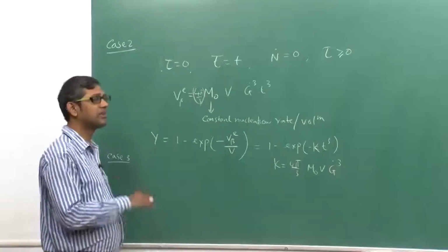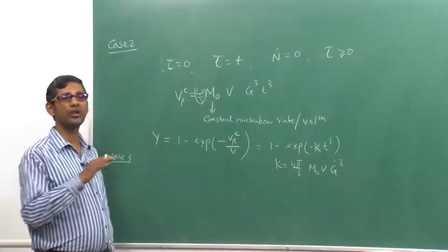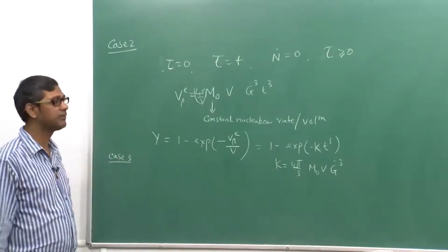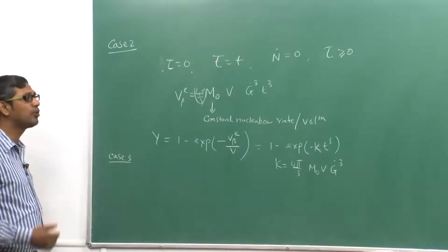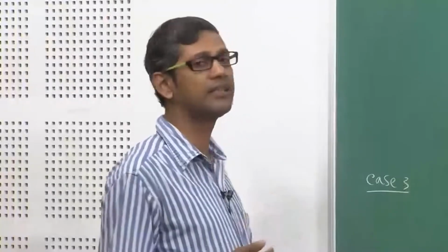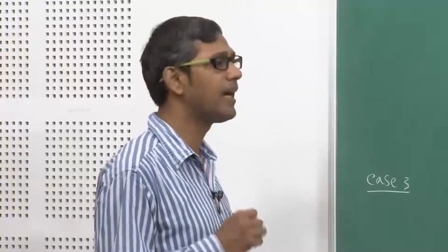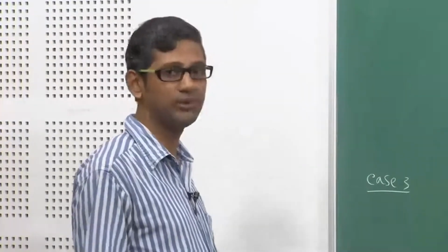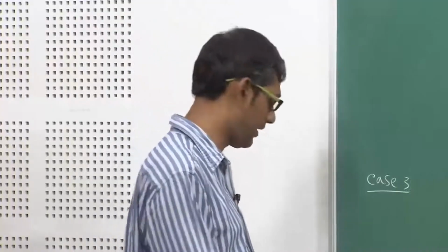So once the nucleation actually happens along all the grain boundaries and it is exhausted, suppose all the grain boundary areas are filled with these nuclei, there is no further nucleation possible along the grain boundaries. The only possible chance is then nucleation inside the grain, and that is very unlikely because of the energetics of the system, which we have discussed many times in earlier lectures.